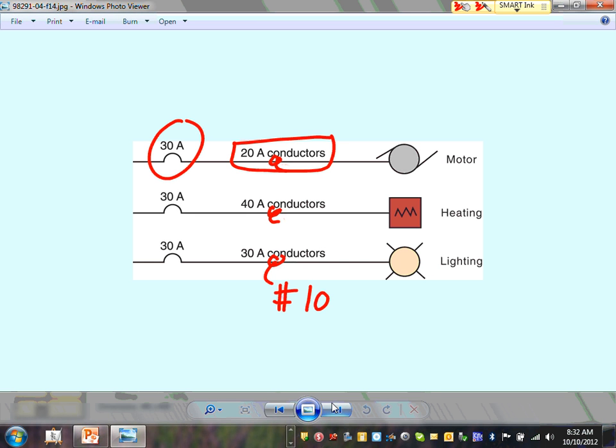They go in the field, they come back and say, Chad, you can't believe what I saw. What did you see? I saw a number 12 conductor tied to a 30 amp circuit breaker. Okay, no problem. What's at the end of that conductor? A motor. Most motors have overload protection, so that overload protection at the end will protect the cable from overload. So that circuit breaker is protecting you only from what? Short circuit and ground fault. So that is the exception, where the conductor does not have to match the overcurrent device or be larger.